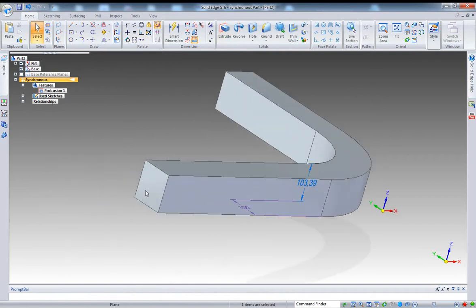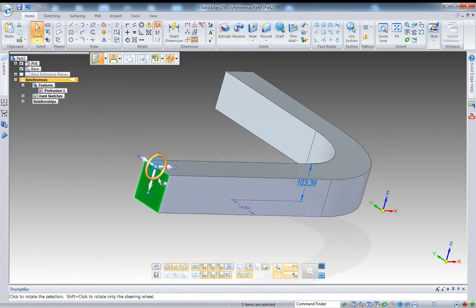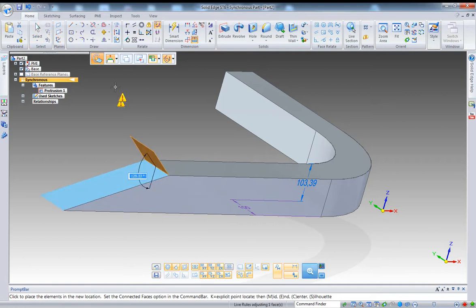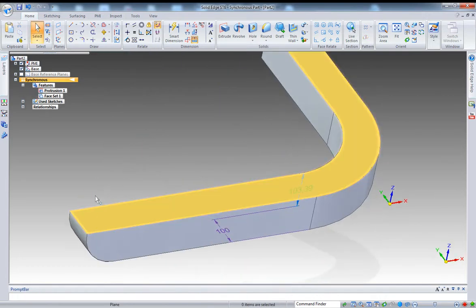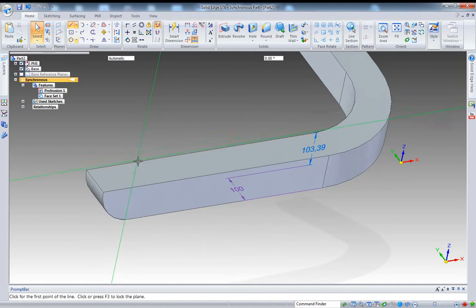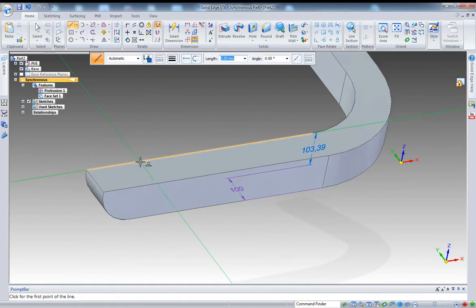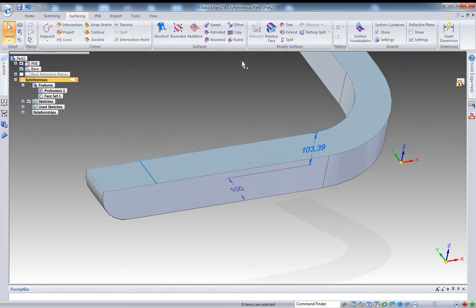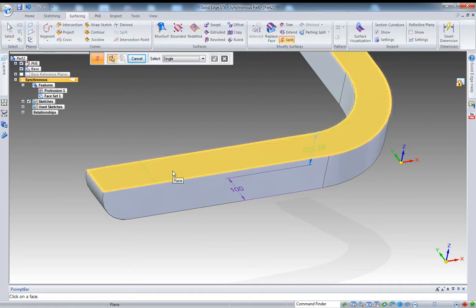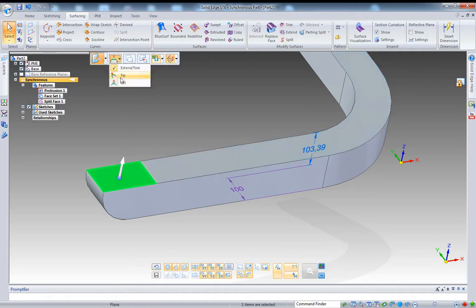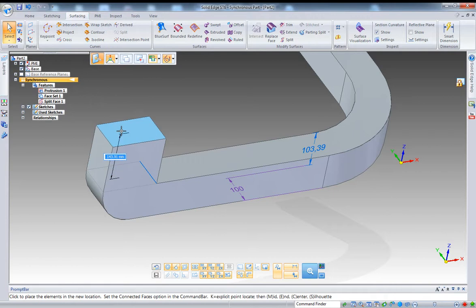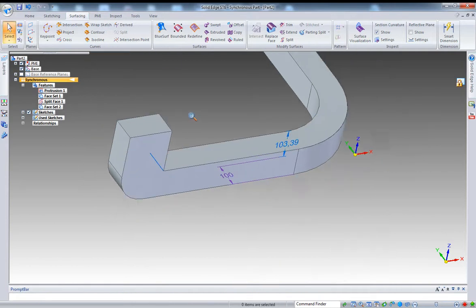And probably I want to add some round, because from what I remember from the video we got a round at, probably I want to lift that face 90 degrees. And since I got no straight face here, what I will do, I will simply add a line somewhere here, and I will use a surface command named split, where I want to split that face against this one here. And now I can use the lift command again and come out with something like this.